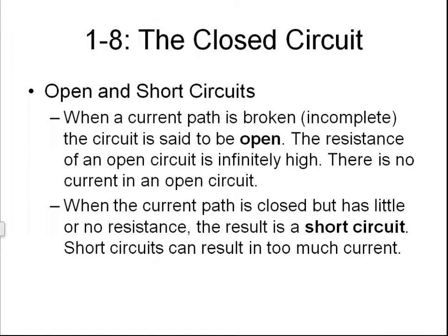All right, problems with any circuit? Well, when you don't have a complete path for your current flow, that circuit is open. The resistance is infinitely high, because unless you're really discharging a lot of current, it's real hard to make air conduct. So if air is not conducting, you've got an infinite resistance, there is no current flow.